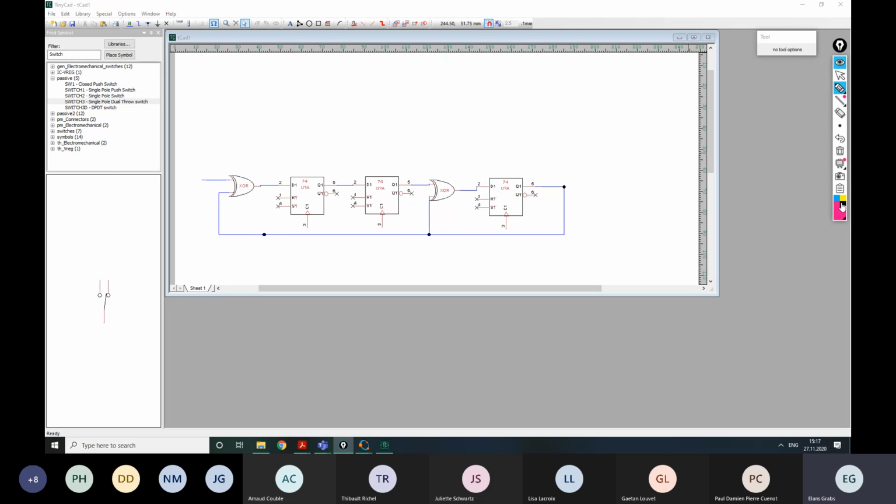Also, please remember that this schematic is drawn for the generator polynomial z third plus z squared plus 1, not the same polynomial as in example, right? In example, it was without the second power here, and therefore that XOR was located here. So that is only schematic required to perform division and find the remainder.